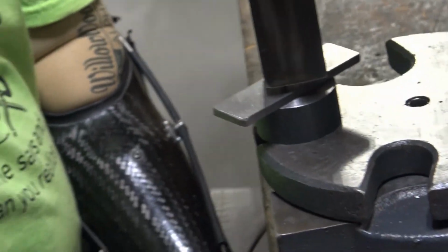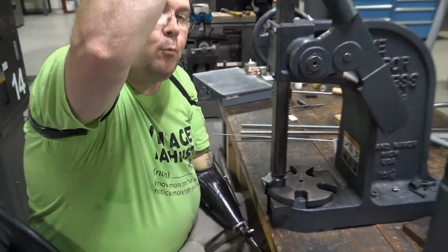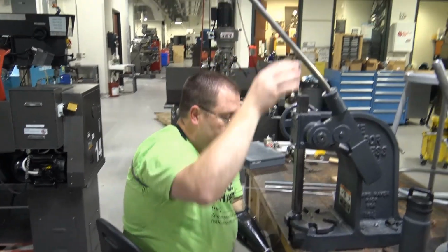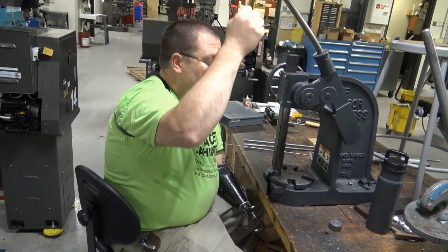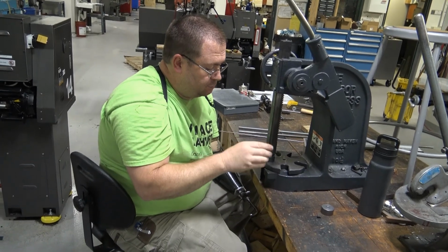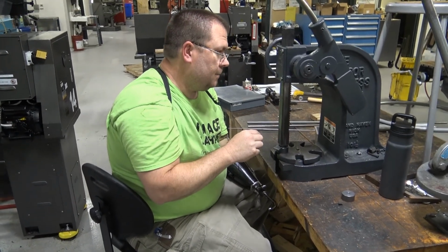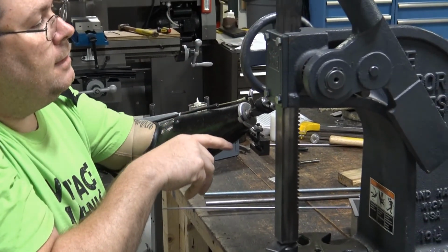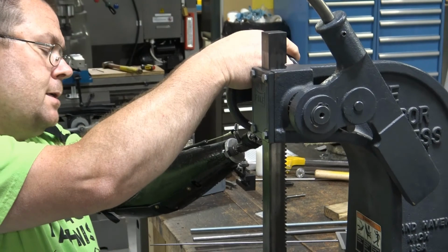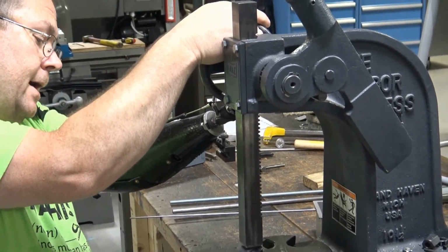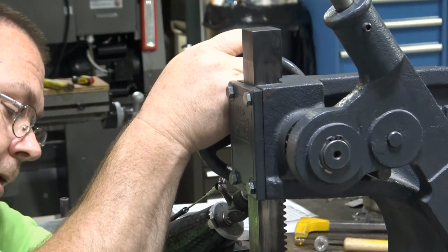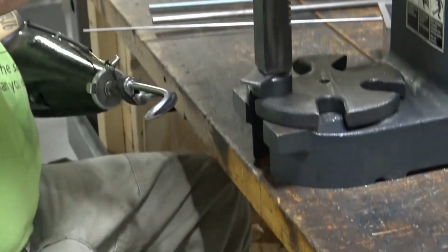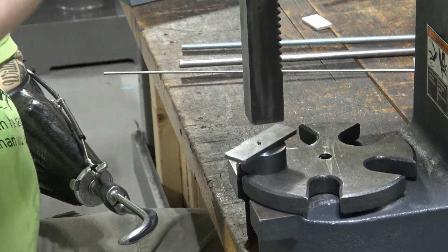Now this arbor press has roughly about 1.5 tons of push force if I grab way out here on the end of this handle. It should be obvious to you that I don't need that kind of intense pressure to press this pin in. So all I'm going to do is use this hand wheel that's on the side of my arbor press, and I'm just going to kind of steer it down in. So as I pull on it, it's going to press down in the hole, and I should be able to feel that, right? Until it stops.